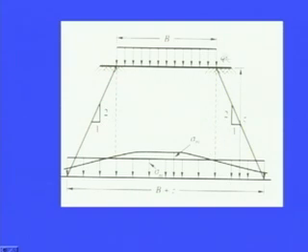So, this load intensity Q is transferred from here at width B to the width B plus Z. In order to find out delta sigma at this particular level, we can find it out like B into Q into unity for the strip footing, divided by B plus Z total divided by 1; that is the load increment or stress increment at this particular level. Actual load increment by the Westergaard or Boussinesq method may be of this type, but the average value we can obtain from 2:1.